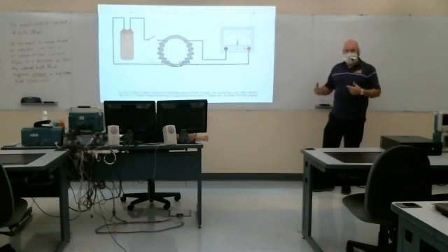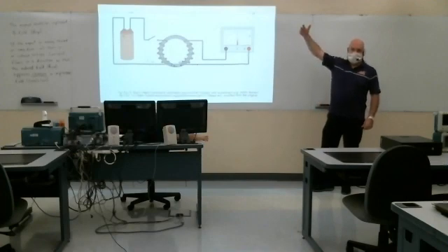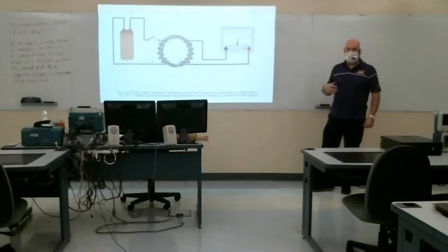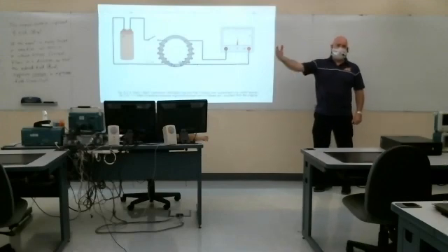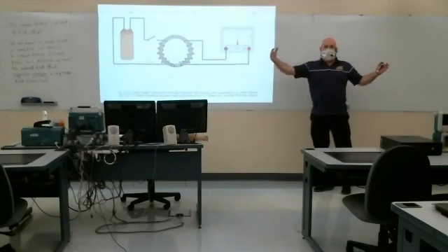So with AC, like our sinusoidal voltage, we can transform that up to very high voltages, which we can transmit long distances at low currents, because power is voltage times current. And if we have to transmit power a long distance over a conductor, we want to do that using very little current to minimize the I²R loss in the conductor. Okay.